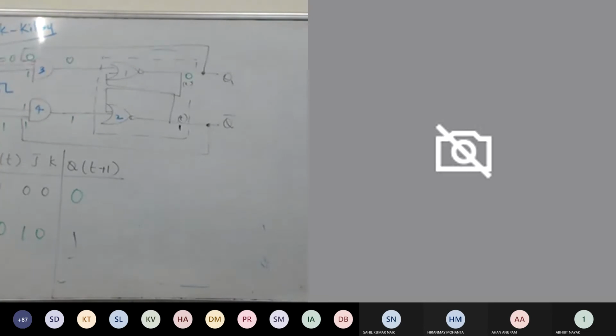What exactly are you following? NOR latch I have completely told you, it's based on a single statement. If any of the input is 1, invariably it will be giving out the output 0. So that has to be understood immediately. That's what the NOR logic is.